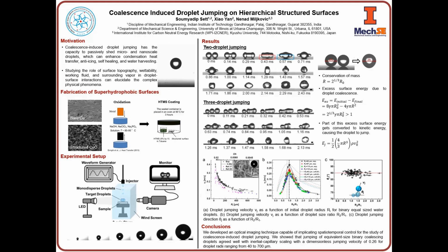When small droplets coalesce on an ultra-low adhesion nanostructured superhydrophobic surface, the excess surface energy is partly converted to kinetic energy, leading to jumping of the coalesced droplets. The nanostructured surface beneath the coalescing droplets reduces the droplet adhesion to the substrate by minimizing the solid fraction and breaks the symmetry of the coalesced droplet. As a result, the droplet accelerates and departs perpendicular to the surface, where the jumping velocity can be closely related to the removal efficiency of droplets from such surfaces.